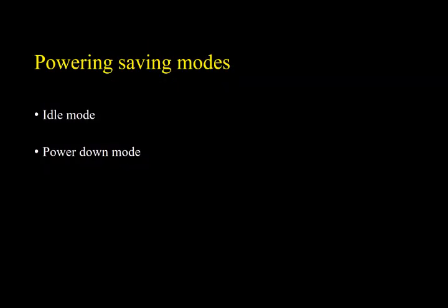So this is one important 16-mark question that you can expect in your university or internal examination. Then this is the power saving mode. The most important point that every one of us should note in 8051 is the power saving mode. The first mode is idle mode and the second mode is power down mode. In idle mode, even if there is a power cut, the data will be stored. But in power down mode, once it is activated, no data will be stored. That is a major difference.